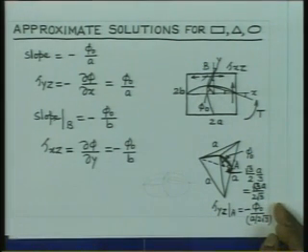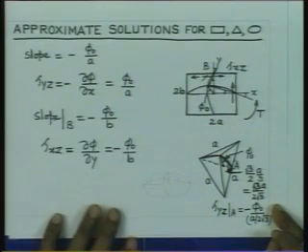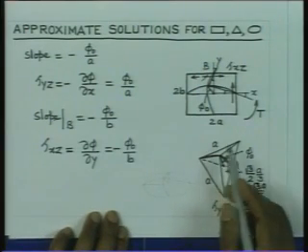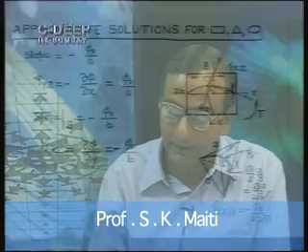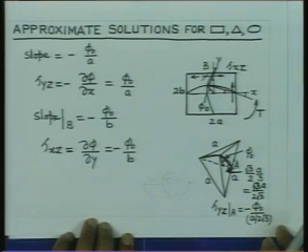And you can obtain this phi 0 by considering the fact that torque capacity of the shaft is given by twice the volume of the approximate pyramid, and hence you can get this phi 0, and you can also obtain the solution approximately.